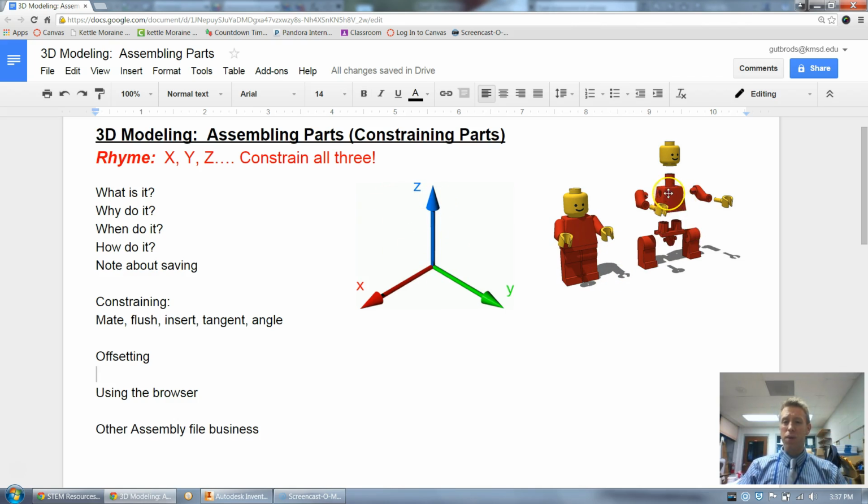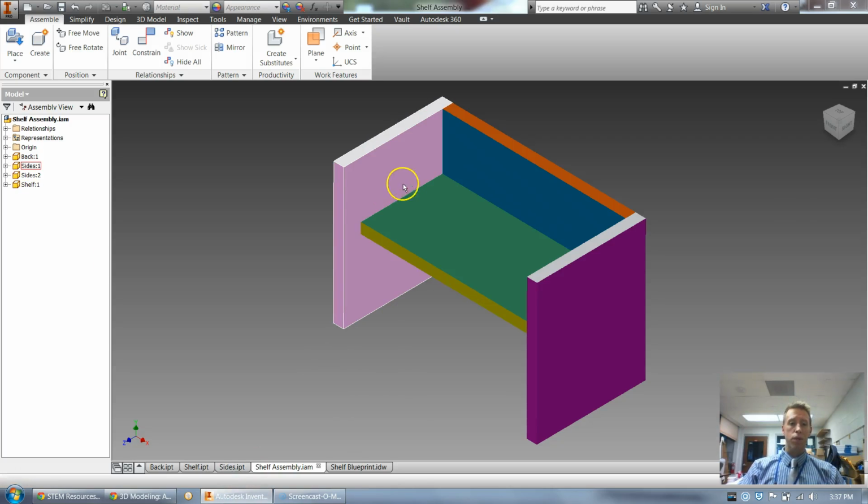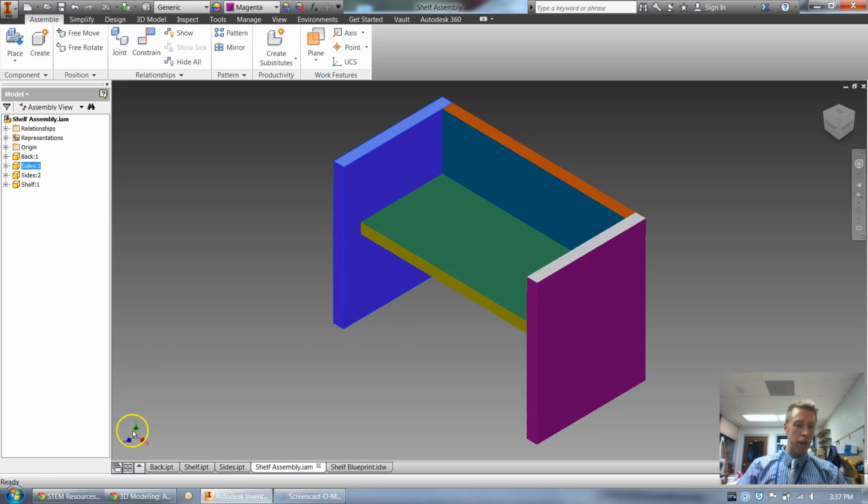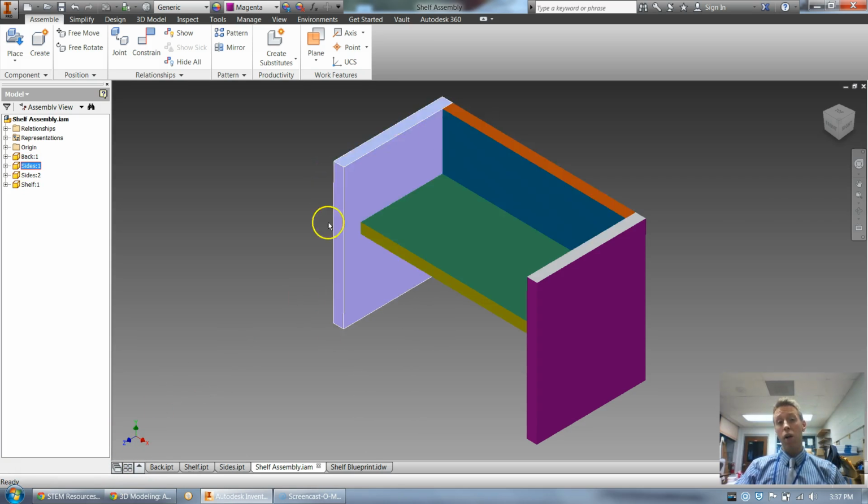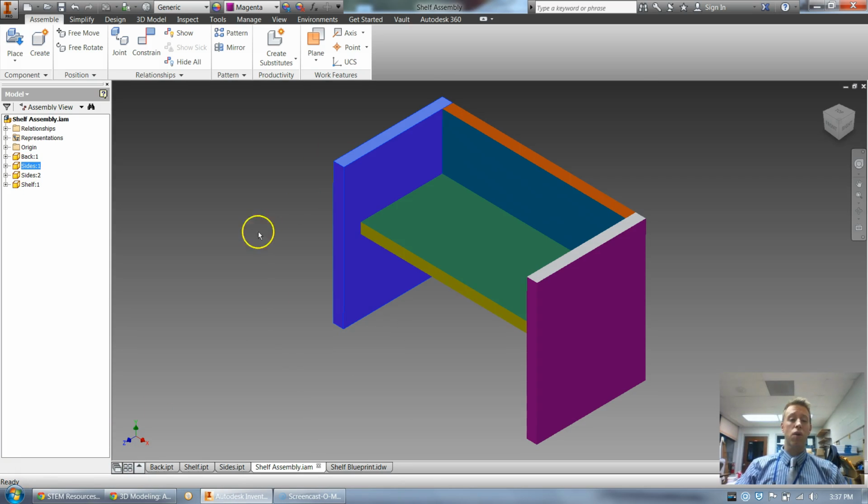The same thing, let's say, with the chest down to this middle section. We're going to tell it 3 coordinate planes. I did that on my pieces here. On this piece right here, I got my coordinate planes. I had to tell it how far up and down in the Y, how far left and right in the X, and how far in and out in the Z. So you're going to have to constrain all 3 coordinate planes.